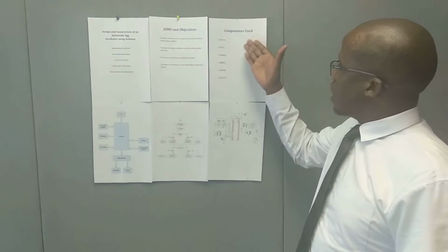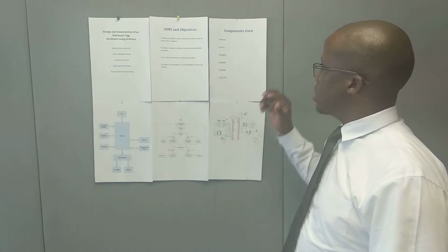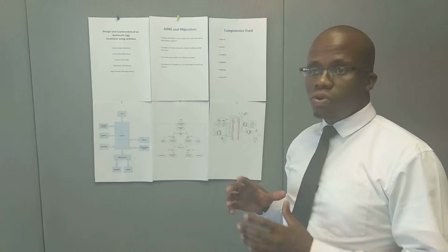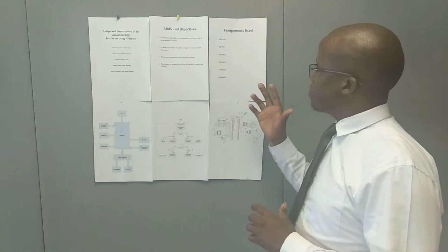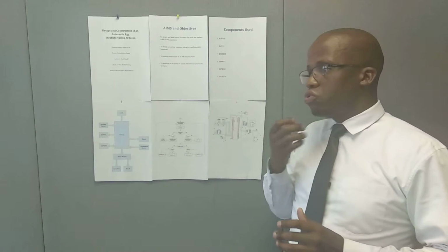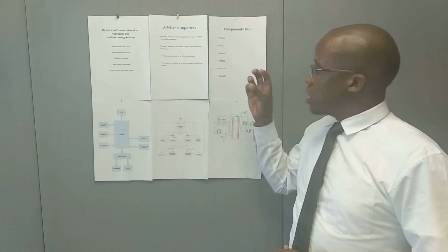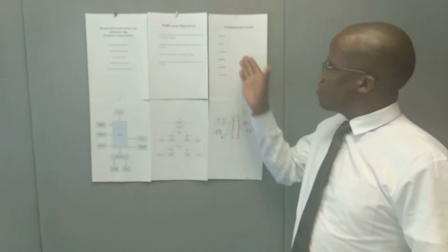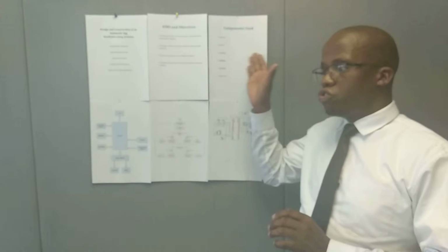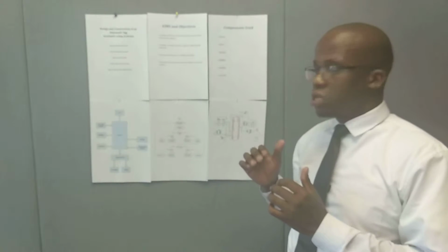The components used in this case are the Arduino, which is our control device, and then we have DHT22 for humidity and temperature. We have DS18B20, which we'll use to supplement the DHT22 in the case of measuring temperature. However, you may find that the DHT may fail, then we can judge due to the readings on the DS18B20 whether the readings are correct or not.